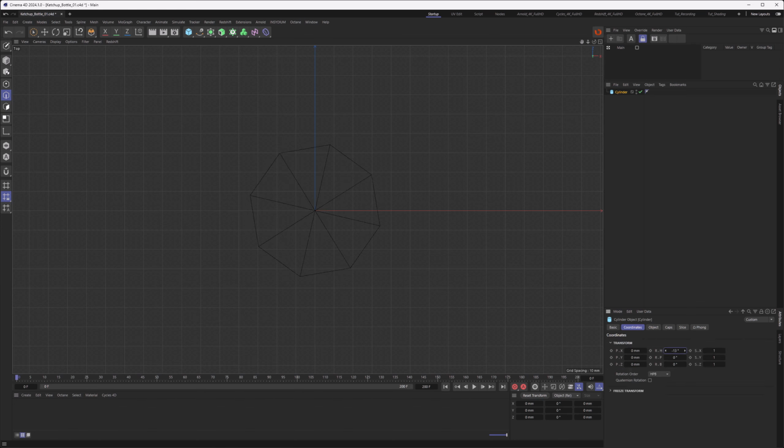So let's go to coordinates and rotate it. Basically we want it to be rotated like this. We have this umbrella logo here, but we want to do it mathematically sound. So what we need to do is 360 divided by 8. This gives us 45 degrees, and nothing much has changed here, but we have a 45 degree here. So what we need to do next is divide that by 2. And then this is 22.5, and it gives us the correct alignment of our faces.